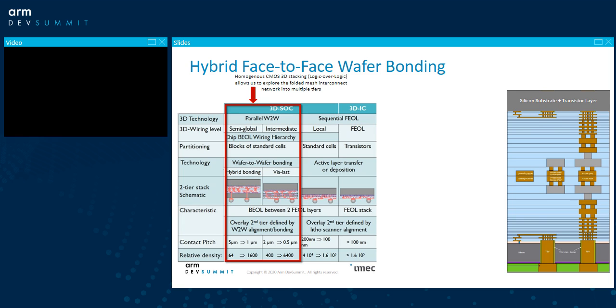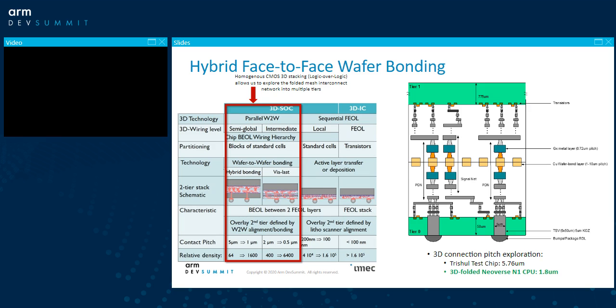So regarding the process details, the bonds are copper. The wafer bonding process, as shown here, is the whole assembly of the 3D stacking design like this. The wafer bonding process is done at room temperature, and a small amount of liquid is used to create a non-permanent covalent bond to initially stick the wafers together in a very precise fashion.